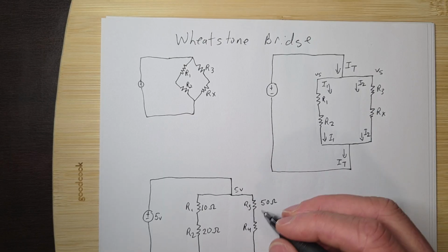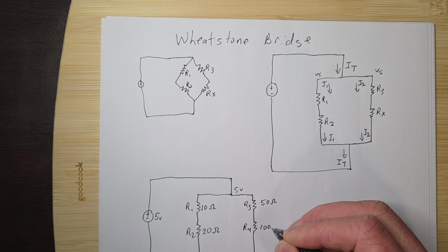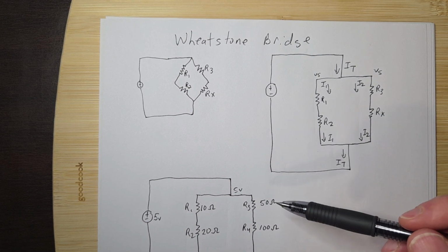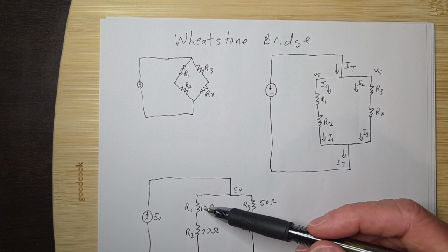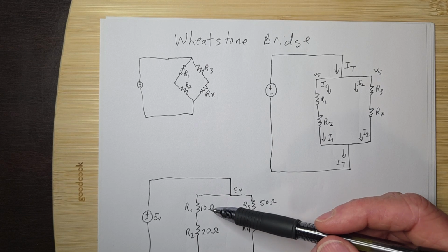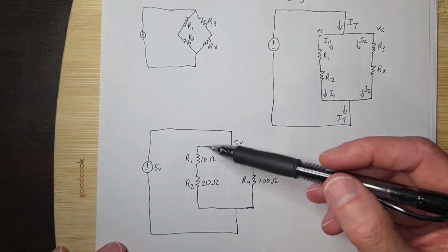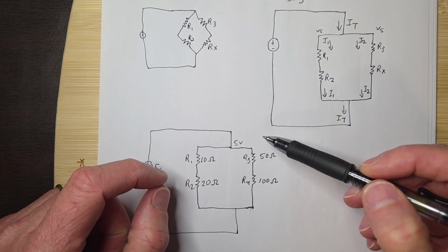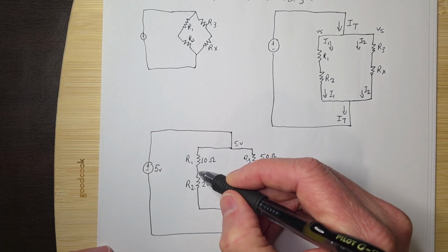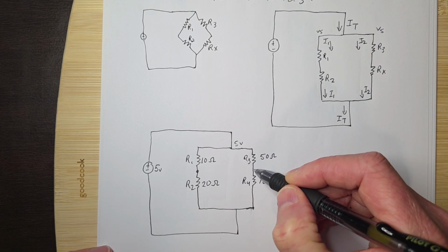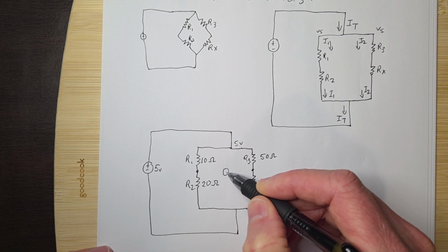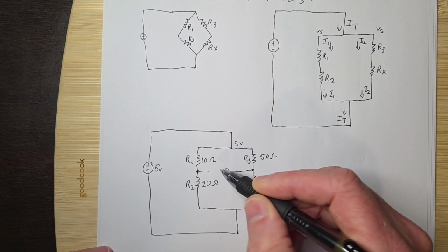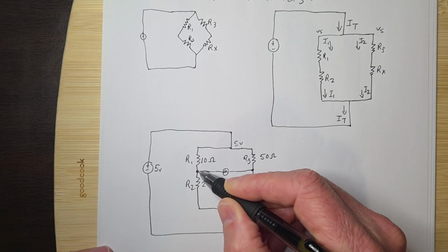to make it easier to understand because we're going to be dealing with a ratio, what I mentioned for ratios. So these resistors, if you notice, are the same ratio because this is a 1 to 2 ratio, which is what we're looking for, because since the voltage is the same, if the ratios are the same, then these measurements right here will be balanced. So we're going to have a meter right here, and we're going to be measuring the voltage, or you could measure current, it doesn't really matter.